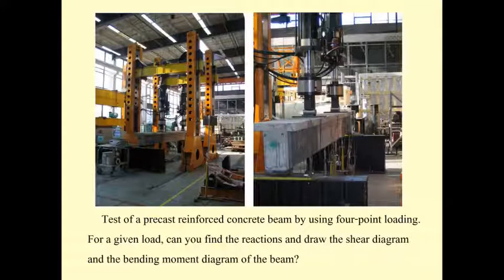I would like you to draw the model of this beam and try to draw the shear diagram and the moment diagram of the beam. With the load transferred by the P like this, the beam will deflect like this. You may see the deflection is measured by using the LVDT, or linear variable differential transducer, over here.